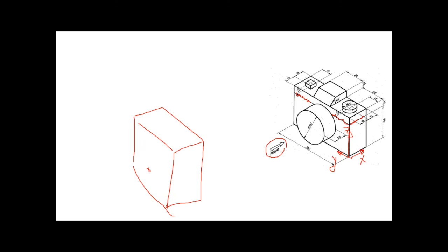And then we locate the center of that circle. You draw a very simple circle here. Remember, guys, to activate this one to become your new XY plane, right? And then you make what? Press pull for that circle to draw that cylindrical part.